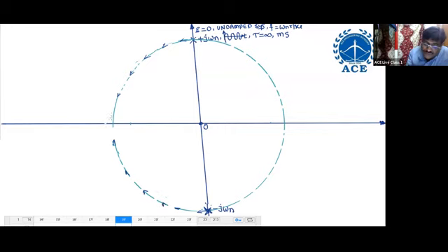Both the poles move towards the left and nearer to the real axis, and both the poles enter the real axis when zeta equals 1. The system is called a critically damped system.